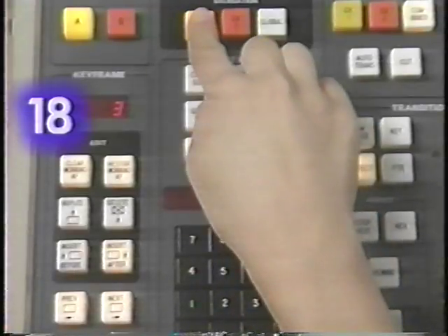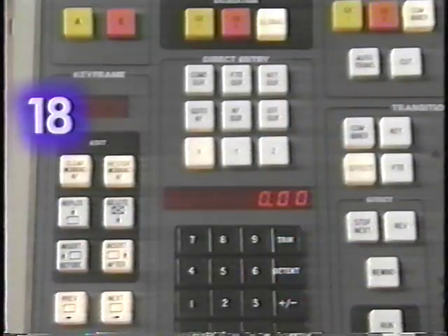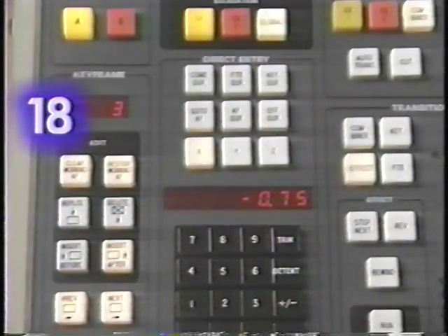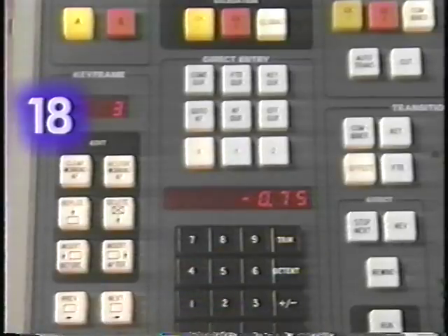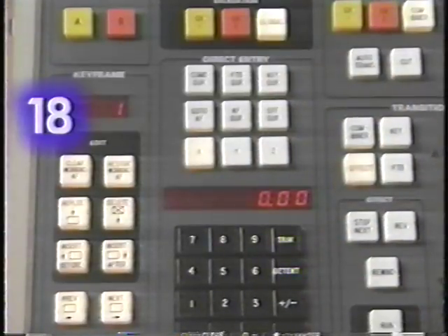If there is a keyframe at a given point for one channel, but no keyframe for the other channel at that particular point, you can delegate to both channels and make modifications to both channels. Note that only one editing function is active in this mode, Insert After. There is no keyframe in the other channel to modify. The result of this operation is that the keyframe that does exist will be modified or replaced. The other channel will have a keyframe inserted at that point.